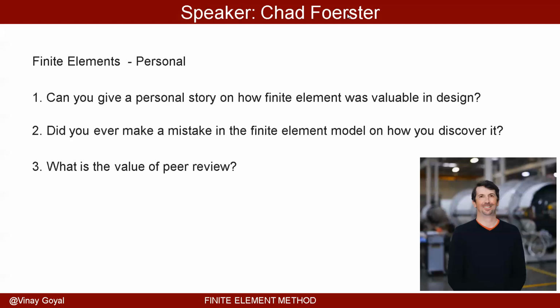And that's when peer review is really checking the final product. But what I want to say is a peer review extends probably even before that to quick pings and checking this and this and this. And did you follow all of your checklist? Are you sure your material properties are right? Did you use the latest rev? Are you sure you checked a certain box so that you're doing an elastic plastic analysis and it's not just elastic, something like that, right?